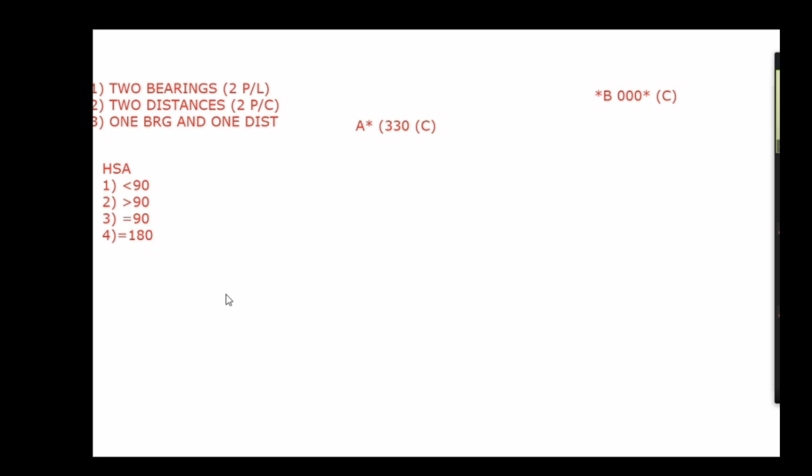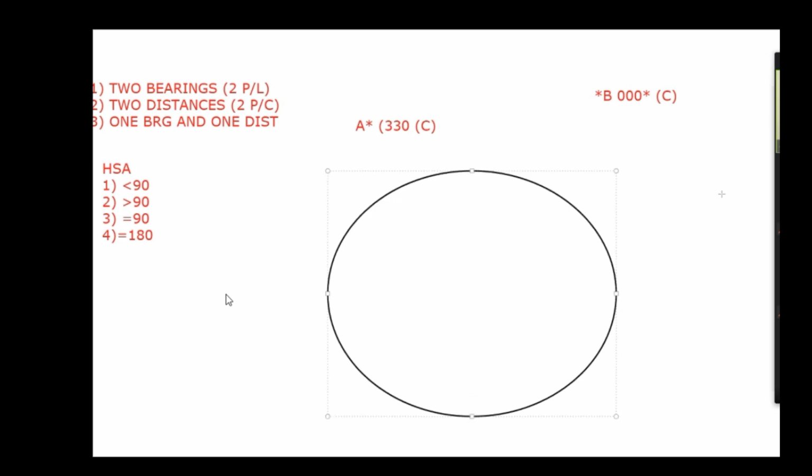On any paper chart there is a compass rose; not only one, there are 2, 3 compass roses in various corners. From there we take the bearings using the parallel ruler, etc. And this compass rose gives you 0 on top, which means true north.